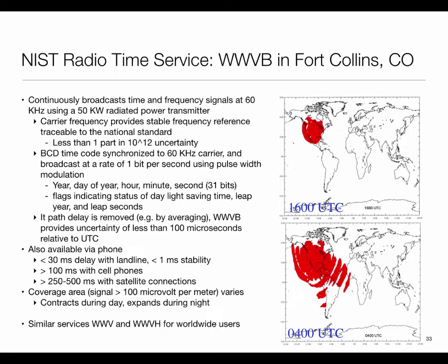What carries on this signal is BCD coded time information. So essentially it's saying time is blah, blah, blah. And then repeating the same thing again and again. And it's binary coded decimal, those following. So year, day of year, hour, minute, second, some flags indicating whether it's daylight saving time or not, leap year, leap seconds, all those kind of things are kind of transmitted. And